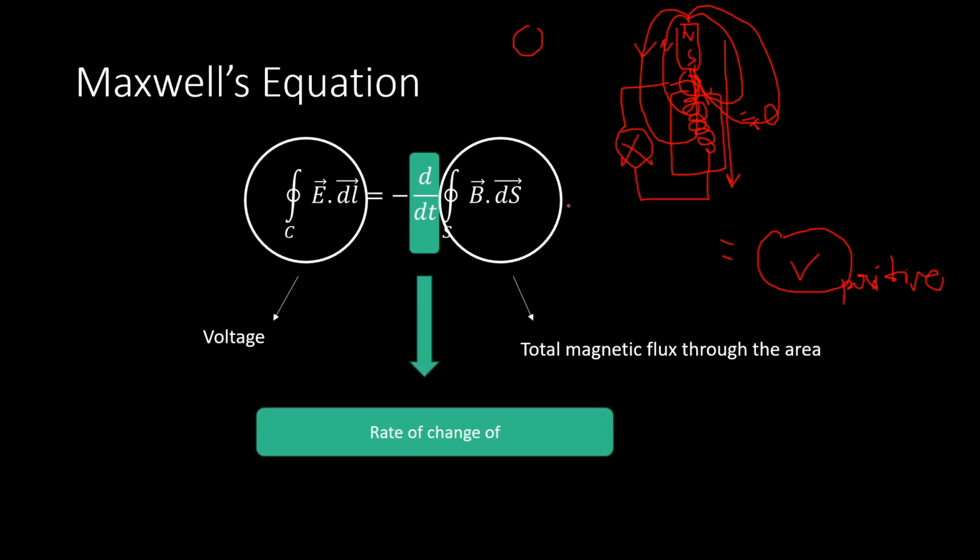So this change in magnetic flux will induce a voltage. And this induced voltage will have the capacity to drive the charge around by generating an electric field, causing an energy transfer. The same thing will happen as the magnet leaves the coil. When it's reaching the end of the coil and it's gone, the magnetic flux will gradually drop from a positive value down to 0. In this case, it will generate an opposite voltage.